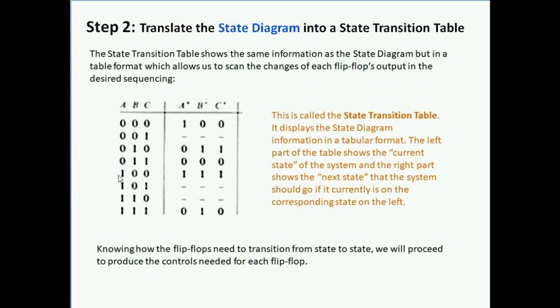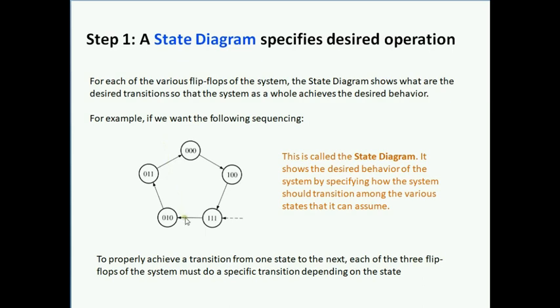But this table has a few more things that are not immediately observable on the state transition diagram, but are implied. So there is a state over here called 001. Now, as you see, the state 001 does not appear over here. With 3 bits, you can have 2 to the 3 different states, therefore 8 different states altogether. And over here you have 5. So there are 3 combinations of 3-bit codes that do not appear on the state diagram.